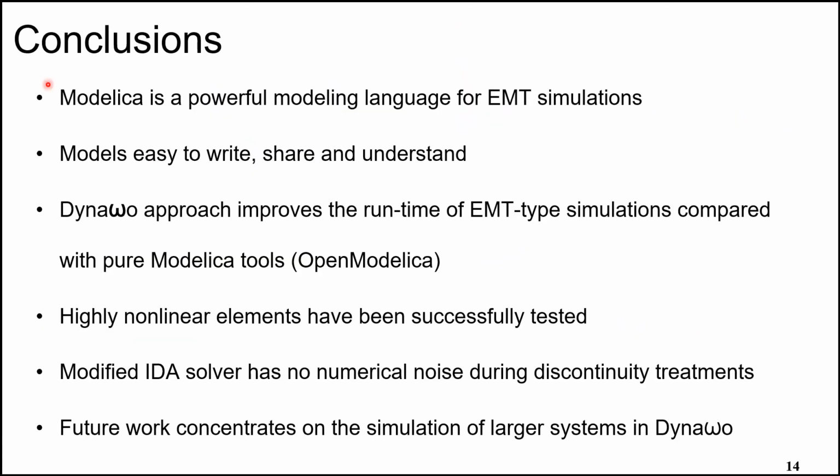As conclusions of this research, we saw that Modelica is a powerful language for EMT simulations. Models are easily coded in Modelica. It's easy to share and understand the code of Modelica. The Dynaωo approach improves the runtime of EMT type simulations compared with pure Modelica tools such as OpenModelica. Highly nonlinear elements such as surge arrestors have been successfully tested with Dynaωo. The modified IDA solver has no numerical noise during discontinuity treatments.